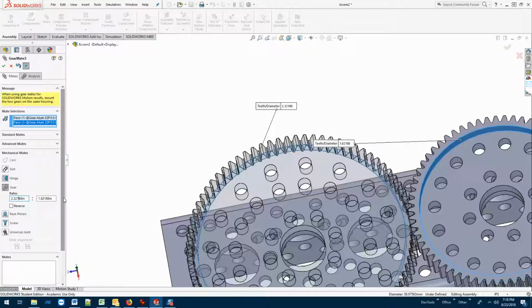It is not that 1.25 ratio. So if we were to allow SolidWorks to set up the ratio based upon these two circles or these two features, these faces that I've selected, it would be close, but it's not exact. And where we can, we would like to be more exact than guessing. Okay? Mm-hmm. All right, so I'm going to stop this video.